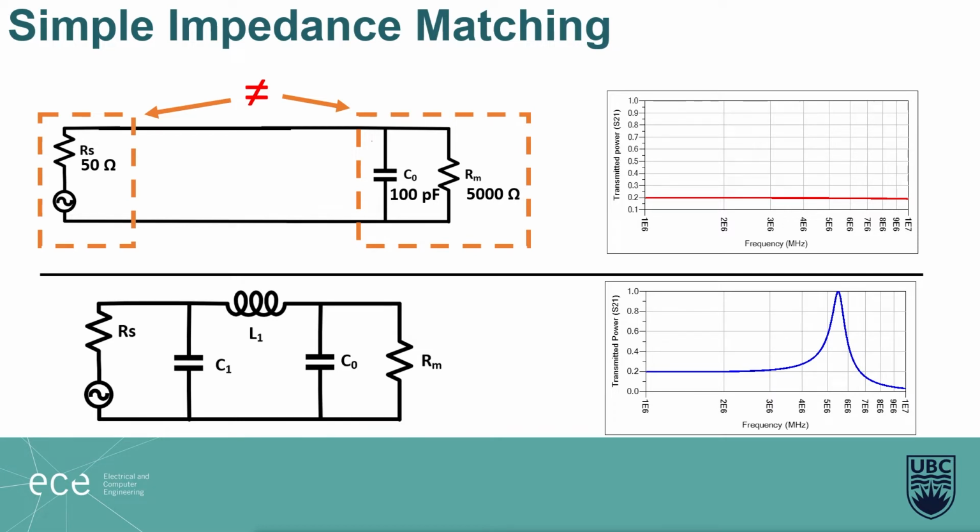On the bottom figure, the simplest form of impedance matching for our poly-CMUT is the pi matching network. A simpler matching technique is a two-element L matching, but it will not work in this case because C0 is too large and cannot be changed. Looking at the bottom graph, we can see a perfect power transfer only at 5.5 MHz. This behavior happens in narrow bandwidth impedance matching. This simple matching circuit restricts the passband frequency, thus distorting the signal shape, with oscillation and ringing.